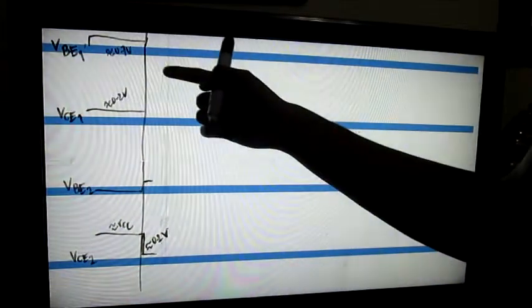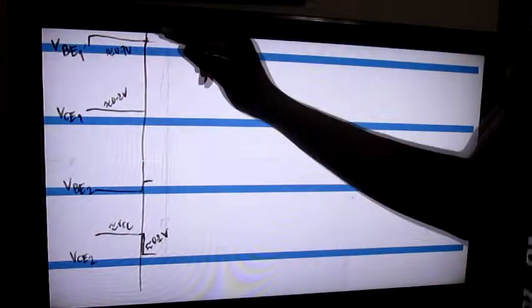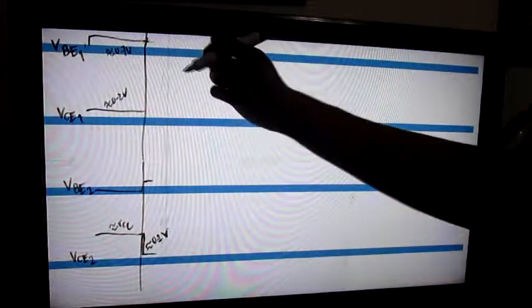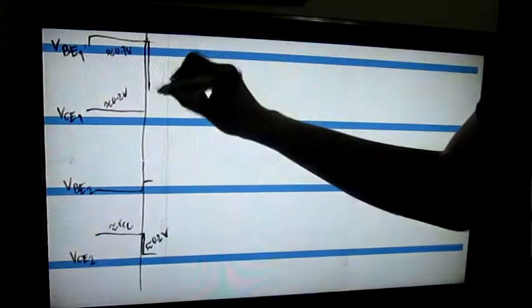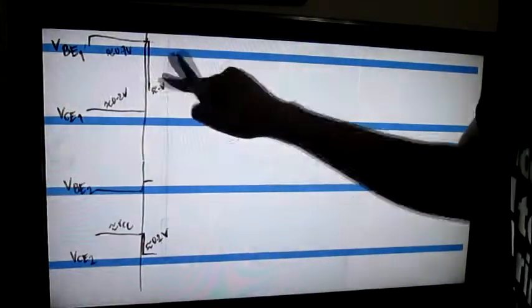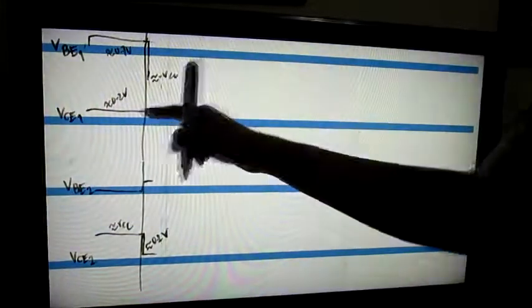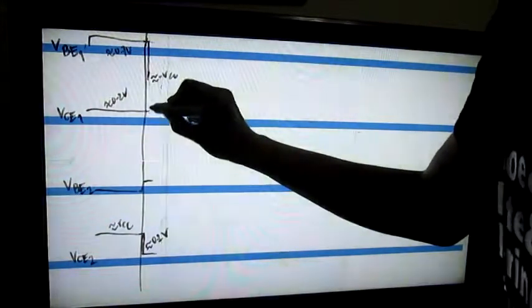At this same instant, the voltage between the base and emitter of Q1 is equal to the voltage stored in the capacitor, which is around VCC minus VBE. For these waveforms, we will assume that it is equal to around negative VCC. At the same time, as Q1 turns off, its output becomes around VCC.